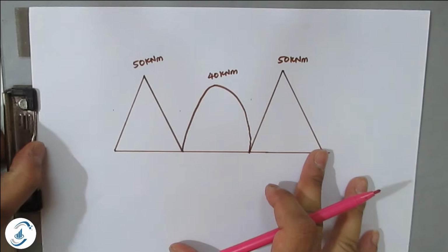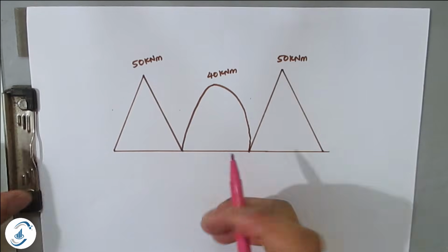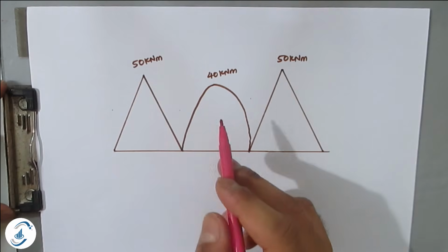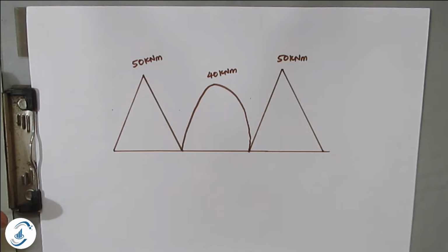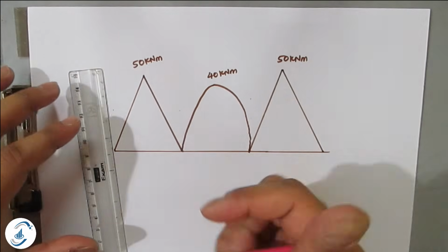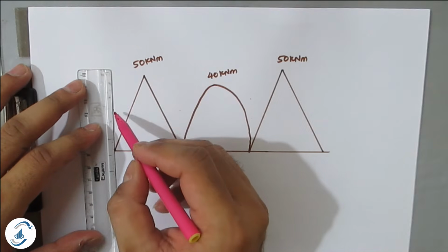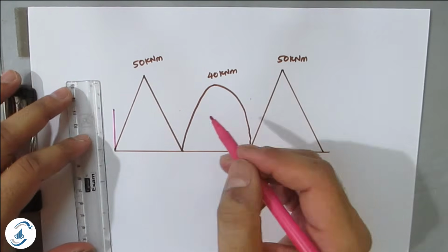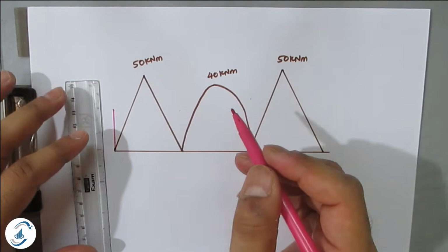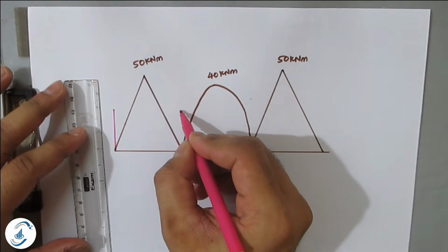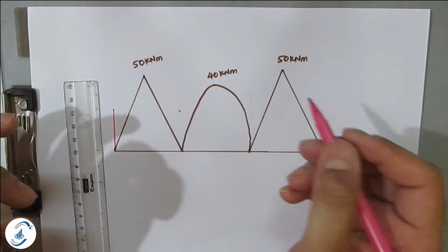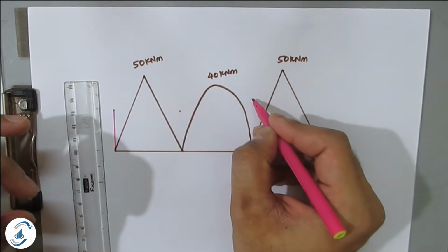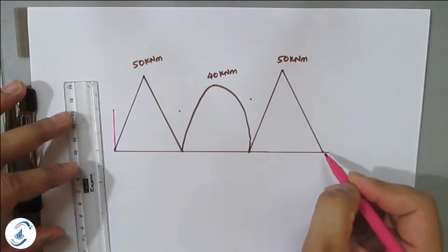Once you get the final moments, then you have to draw the bending moment diagram. This bending moment diagram is with respect to the original loading condition, which I have drawn. Then you have to overlap the final moment values. AB was minus 25, so this will be your minus 25 value. Next, BA BC was 24.236, so somewhere near 25 only will mark here. Next, CB CD is 32.68, so you can mark it here, and this value was 0 here.